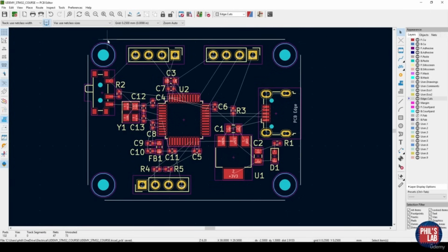So now you can see I've drawn 4 lines, 2 horizontal and 2 vertical at the sides of the PCB that I want. I haven't closed them up yet because I would like to make rounded corners. You can also see we might have to move the connectors around a bit to make sure it looks nice with the board, but that happens with iterations and when fine-tuning this design.